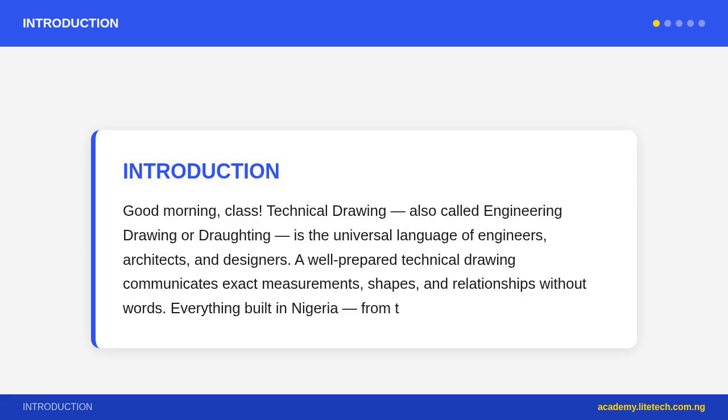Set squares, also written set square or triangle. 45° set square, an isosceles right triangle with angles 45°-45°-90°. Used with the T-square to draw lines at 45 degrees, 90 degrees, and combined angles. 30 to 60 degrees set square, a right triangle with angles 30°-60°-90°. Used to draw lines at 30 degrees, 60 degrees, 90 degrees, and combined angles.